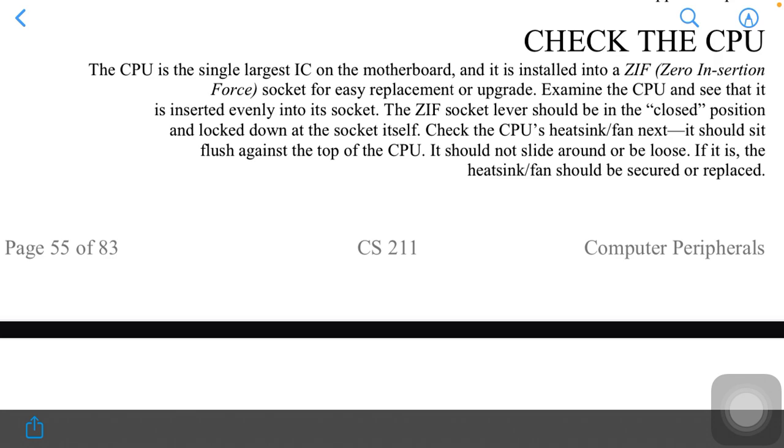So you can remove the CPU, the microprocessor. Remove it. Be careful when you are putting it back. You need just zero insertion force. You don't press it. You don't need a clicking sound. When you drop it, it goes in by itself without any force. Zero force. So you can examine it. Replace it to check. Probably that's the problem. All that, you can read more.